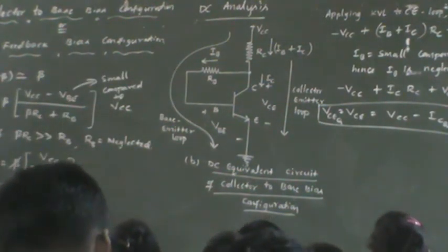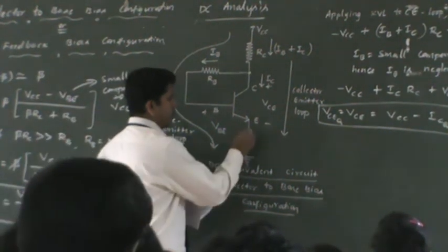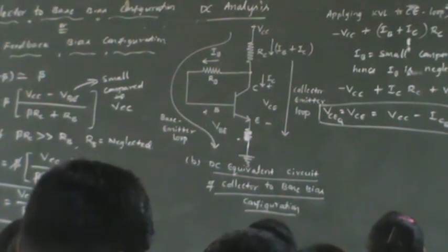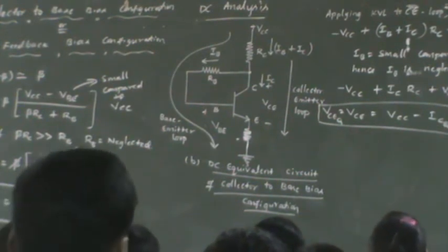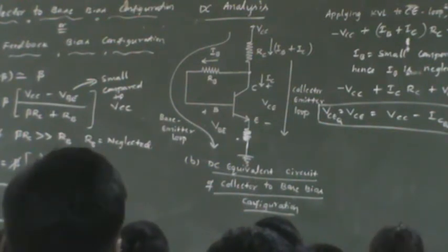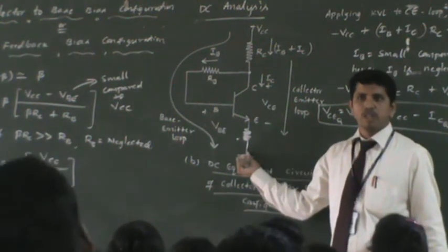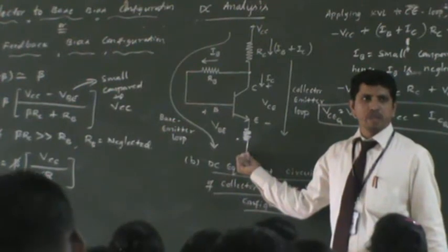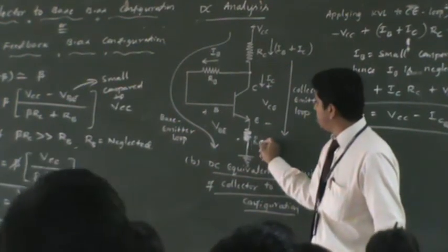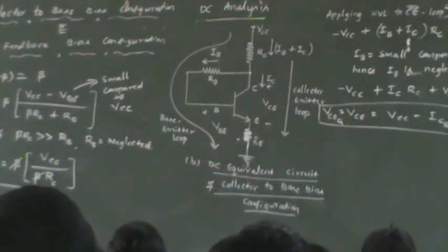So there is a modification for the circuit as we said here. Now can we rewrite the original amplifier circuit by adding an emitter resistor and see what the expressions for IC and VCE will be, just by using some intelligent concept, without deriving all these things? Can we obtain the expressions for ICQ and VCQ? Look at this. Do you understand my point? The modification here is that I've just added the resistor RE. Now I am asking you, can we obtain the expression for ICQ by inspection?